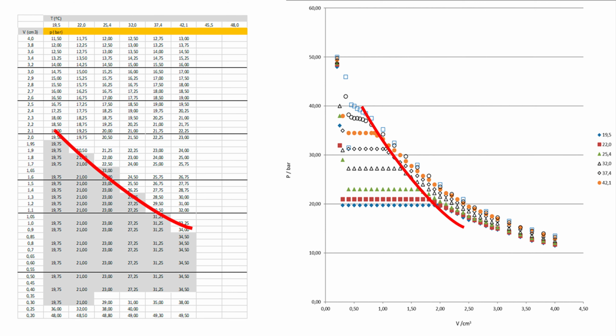On the right side of the PV diagram, we can see the sequence of saturated vapor states. These states of different volume, pressure, and temperature have in common that they are the states in which the first liquid drop appears in the heart of the gas. By means of an isoline, we can link these representative points. In the states in which we have not taken a measurement, this curve offers a prediction of its approximated situation.